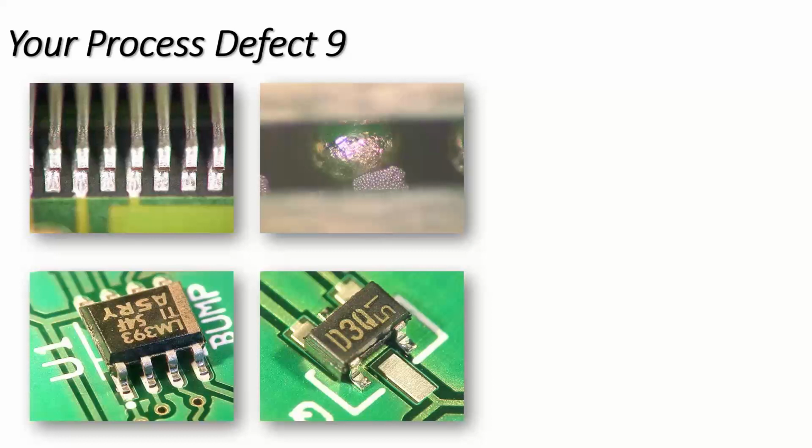Normally speaking, you'll probably find your stencil manufacturer modifies the data to start off with, and that's not uncommon practice. But please check your check plots. A lot of companies get check plots back from the stencil manufacturer and just say, yeah, that's okay. I'm not diminishing the problem, I'm just saying that we don't check it ourselves. So yes, I think the data can be changed, inform the customer, then there's no comeback, but you are ultimately trying to do the best job you possibly can. So I would say, yes, you can change data.